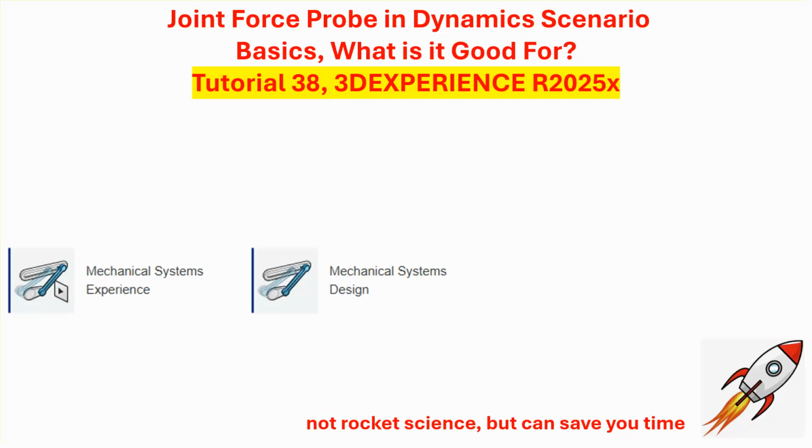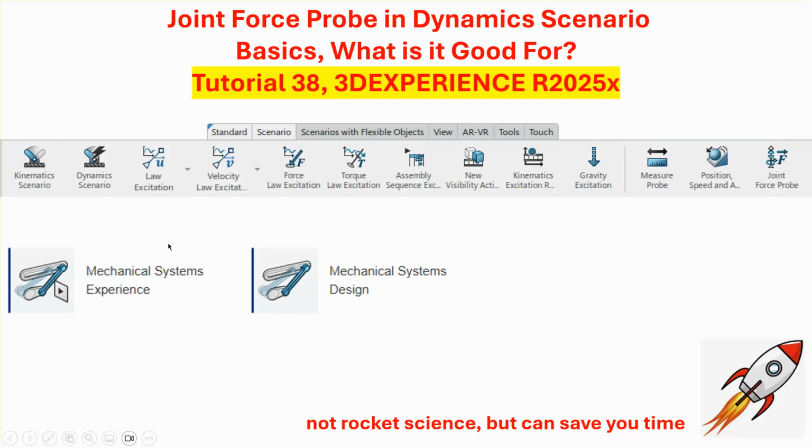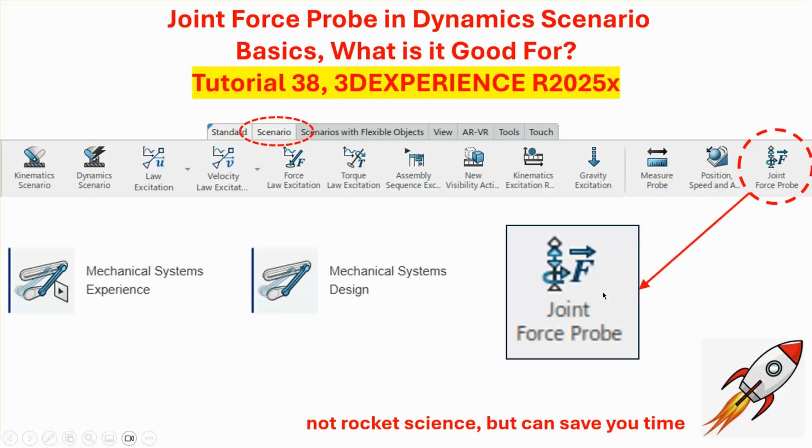Good day, folks. This is tutorial number 38, and I want to show you a few things about the joint force probe icon that appears in the mechanical systems experience where you are trying to do rigid body dynamics. When you go to this application, mechanical systems experience, and you select the scenario tab, what you see is this ribbon of icons, and the particular icon that you're interested in is called, right here, Joint Force Probe, and it looks like that when you enlarge it.